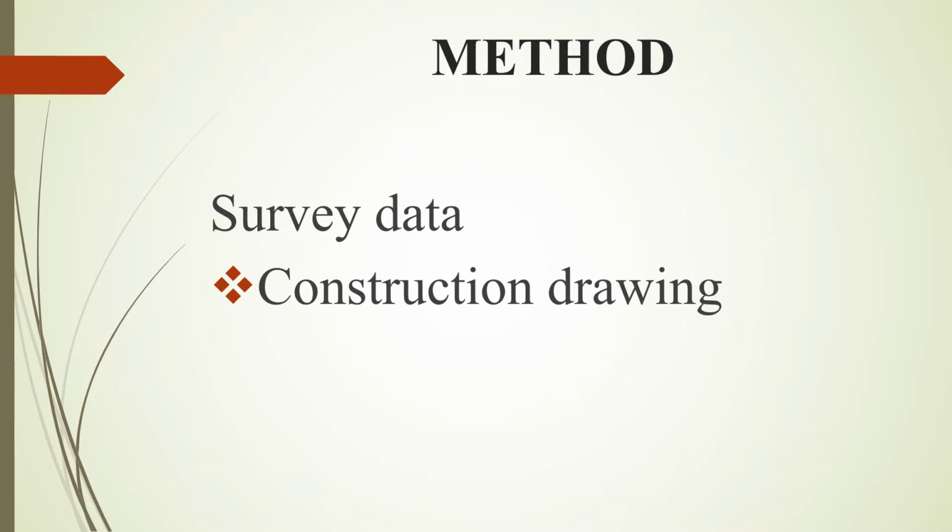Method. Survey data. Coordinates for the position and reduced levels of every structure must be calculated first from the construction drawing by using the software AutoCAD. The construction drawing, which is not in true orientation, must be superimposed with the survey plan before proceeding with the calculation of the survey data.